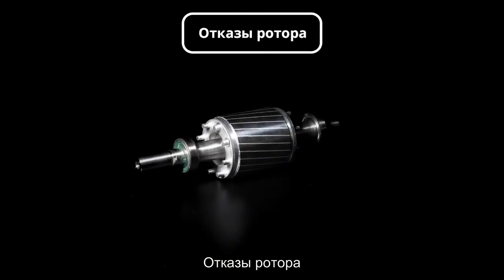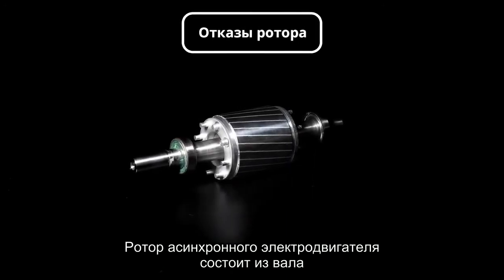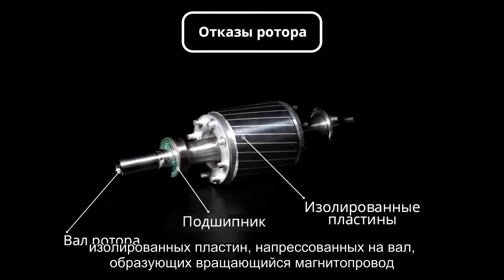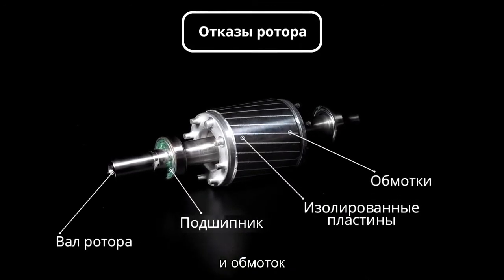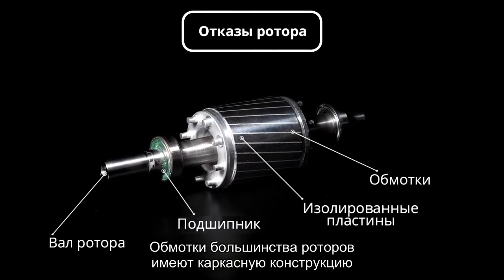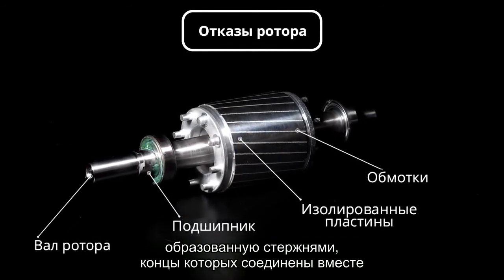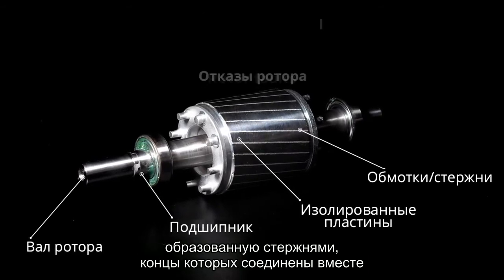Rotor faults. The rotor of an asynchronous motor consists of a shaft, insulated sheets pressed on the shaft which form the rotor magnetic circuit, and windings. Mostly the winding of the rotor consists of a cage structure, which is formed by bars, which are connected at the ends.